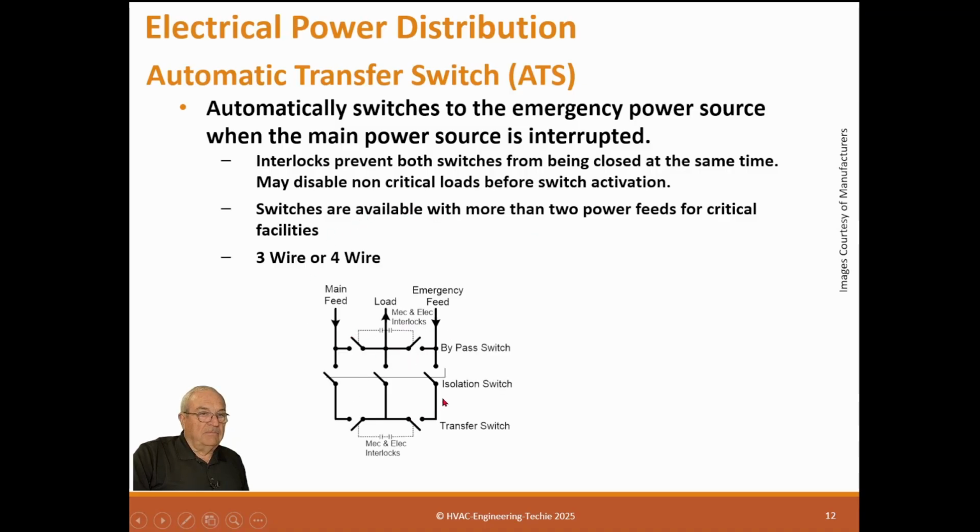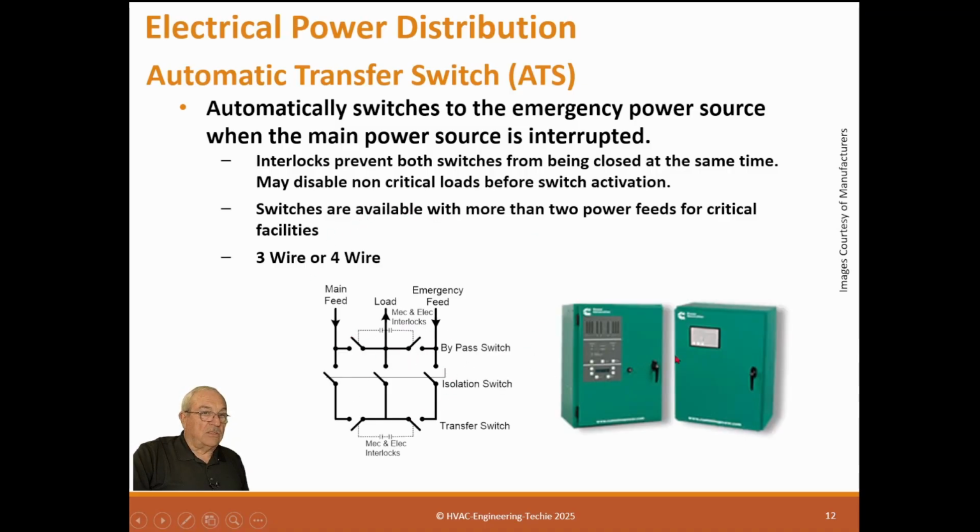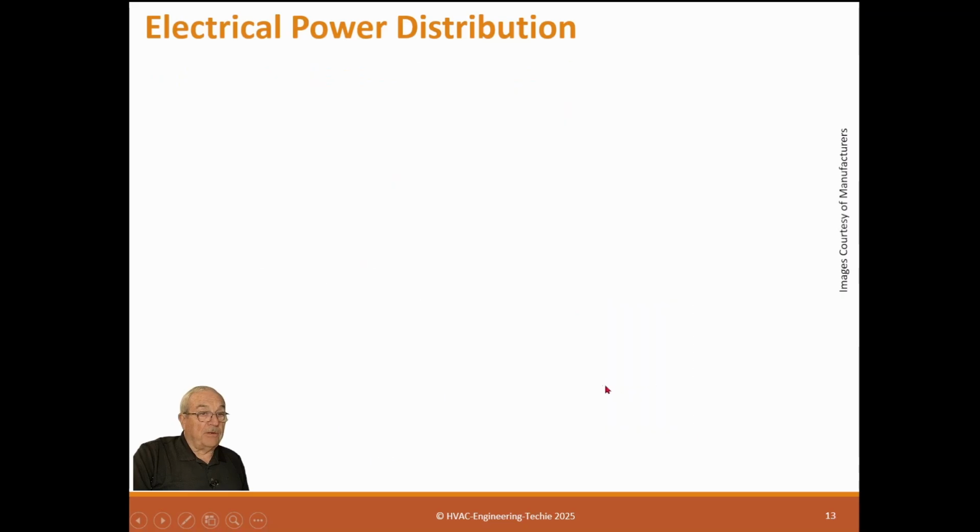And they can kind of look like the circuitry, and some of them can be free-standing if they're big ones. Sometimes there can be a whole switchgear section that's an ATS. It might have 10 or 15 or 20 or 30 switches and one transfer mechanism, so they can be very, very large. And this is the way they transfer power between the generator and the normal load when it's on emergency or standby power.